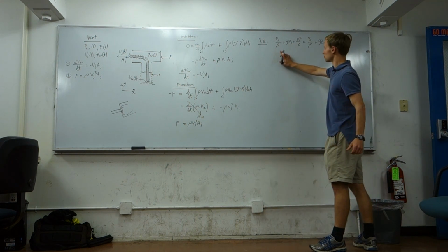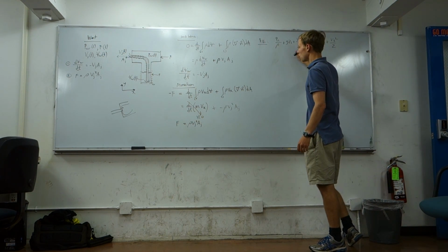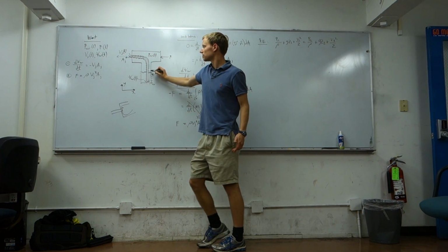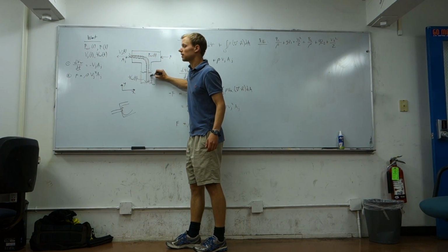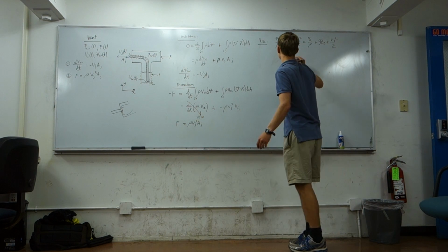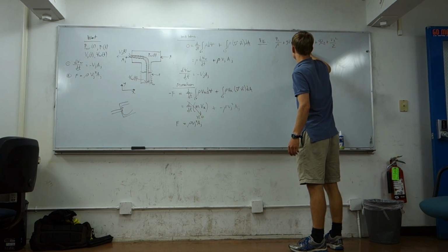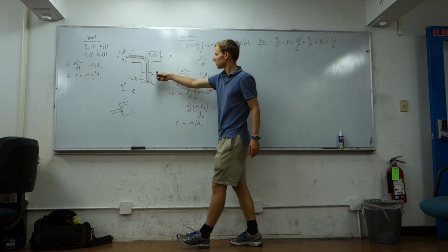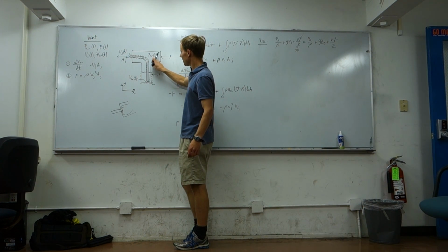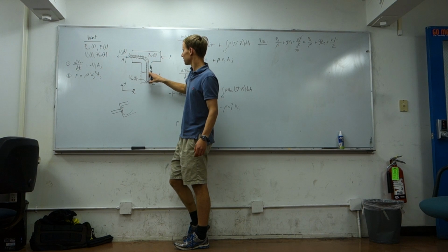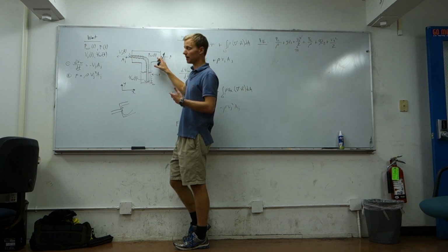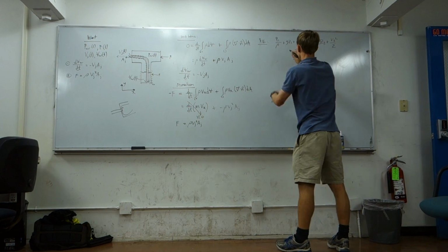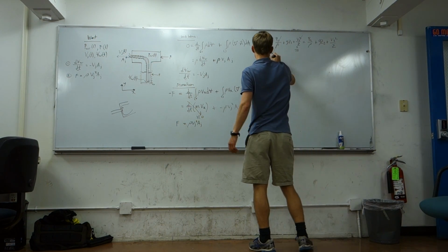So let's drop terms here. First, what's V1? V1 is the velocity at this point here. And we're going to say that's small relative to V2 because this is only dropping slightly in the y direction, but only slowly. So V1 will go to 0. Now, P1 is our P-air, but P-air we know is measured in gauge pressure, so the absolute pressure will be P-air plus P-ATM. But P2 is P-ATM, so we can say P1 minus P2 is just P-air.